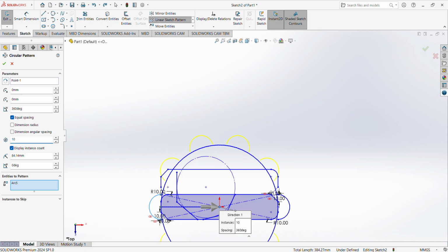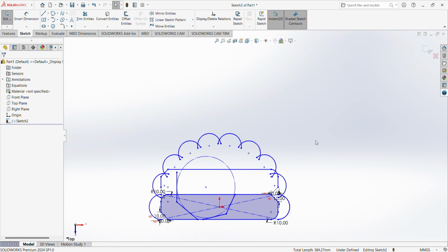It chooses 10 around. You can also decide to just make it 180 degrees, depending on what you are working with. You now have something like this. So it just depends on what you want to do. This was the shape or the pattern I wanted to go around in a circle. So this was it, 180 degrees 10 times. So it automatically does everything for you.